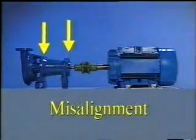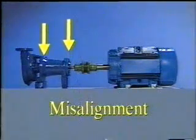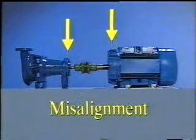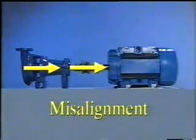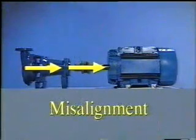Because of this, phase readings in the vertical or horizontal direction from one end to the other will be 180 degrees out of phase. Across the coupling, there is no phase shift in the horizontal or vertical direction. However, in the axial direction, there is a 180-degree change across the coupling. Remember to account for the direction of the sensor for these axial readings.